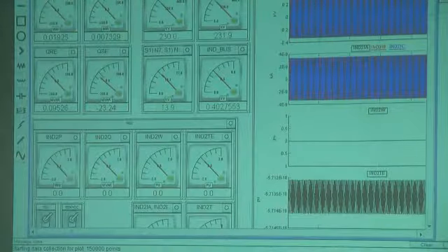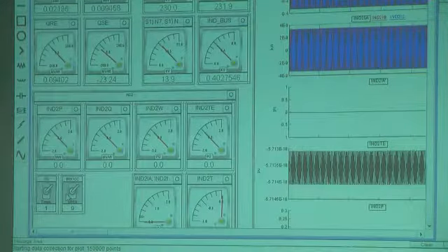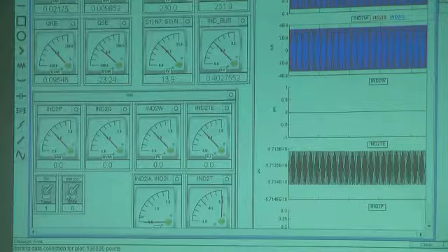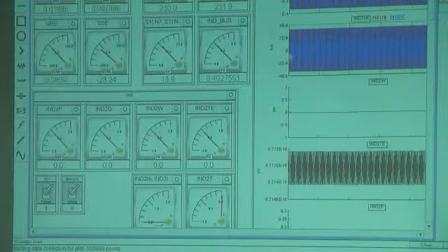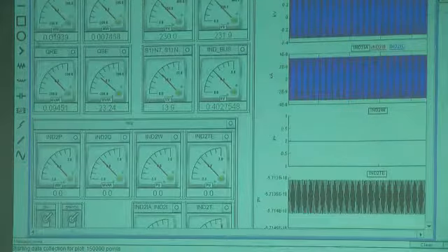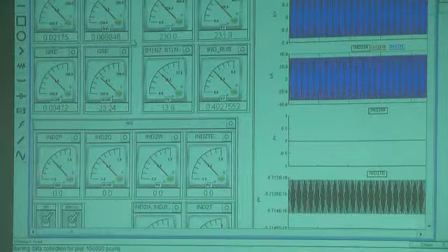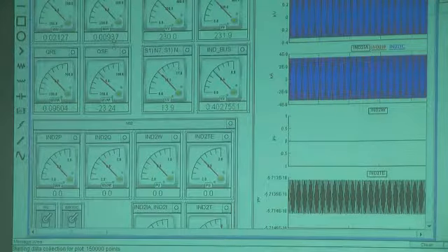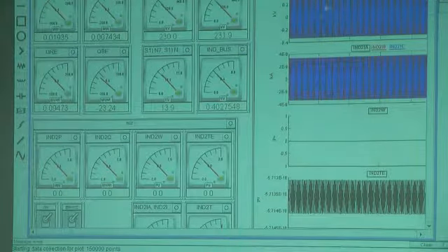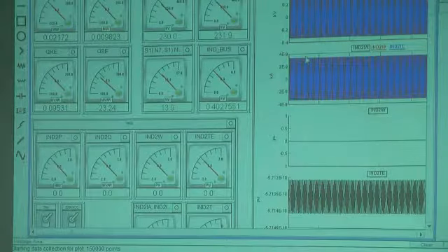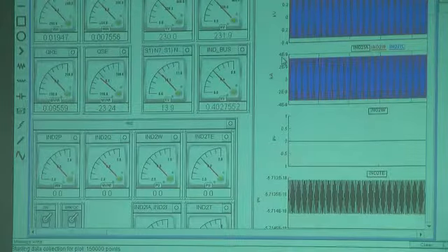So the simulation starts here. We have our breaker open, so the induction motor is not connected. The speed torque switch is set to torque. It's running. There's very little power being sent from the source, and they're basically nothing, 4e to the minus 9.